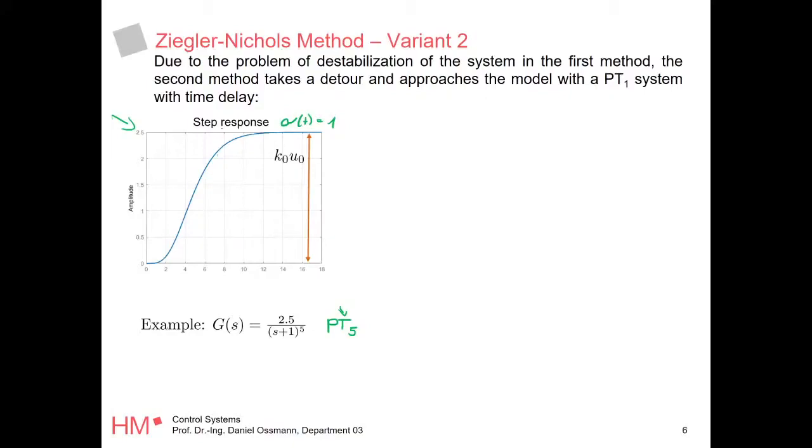Okay, so you do the experiment and you say, I put in 1 whatever kilowatt, and then you record, it goes to 2.5. You immediately know how to calculate your steady state gain. It's taking this 2.5, dividing it by the input amplitude, which in this case is 1, so the answer must be 2.5. Okay, the second step is now you go to 63%, right, of your answer, and 63% of this 2.5 is about 1.6. You go here and you note this time here.